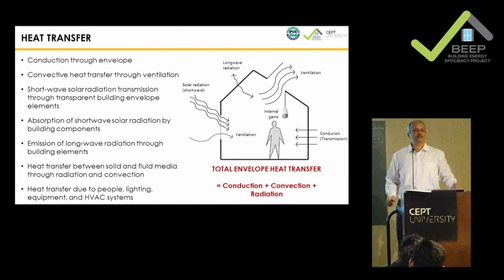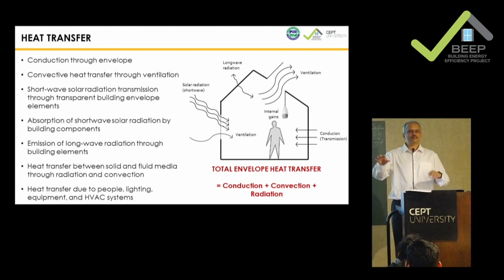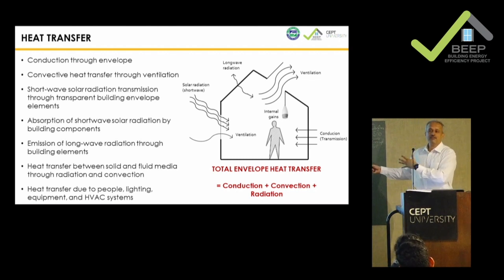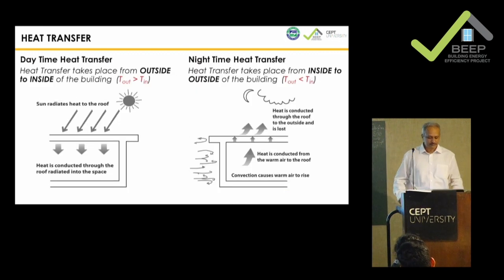If we reduce him, it'll be like an incandescent bulb, right? Basically, the amount of heat which he can dissipate through a 5 foot 9 inch or 6 feet body, he will be doing that with a 4 inch by 4 inch cuboid, and hence the surface temperature will go up. So that's the amount of heat we are also generating inside. That's what internal gains are.